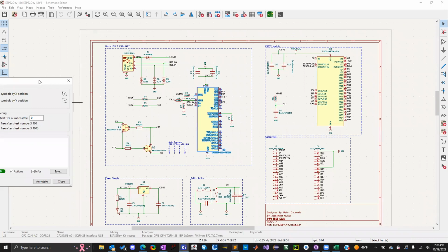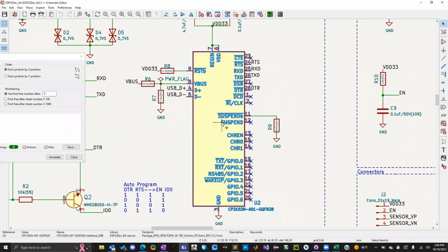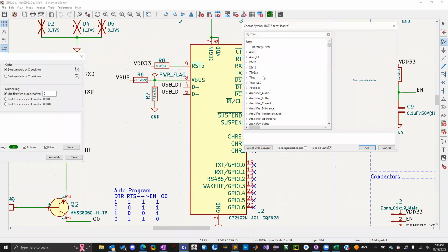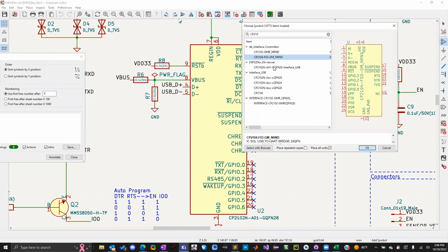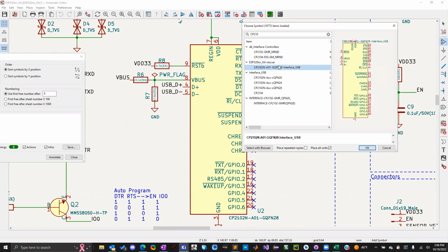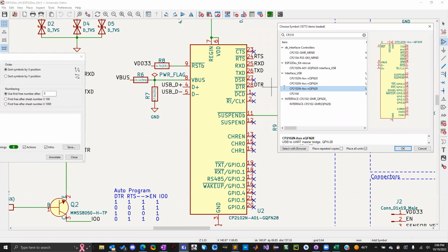The first thing I want you guys to check. Oh, you know what? There were two concerns. The CP2102 here, some students weren't able to find, and that's because I had an imported version. So you can use, I believe this is the one I imported, as long as you use this QFN28 CP2102NA XXX, and the X are like wildcards, those could be any number, any letter, whatever. It will work for that device. So this is the one you will use, and then just make sure you have the same connections, which looks identical.